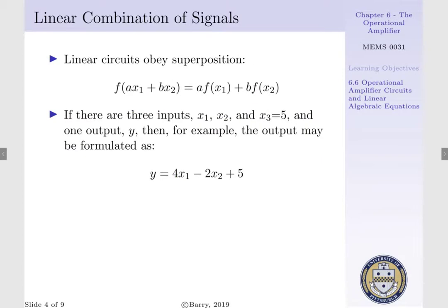Now, before we talk about designing operational amplifiers, we want to introduce the concept of superposition, that is, superposition of linear combinations of signals. Say we have a function f that can take ax1 plus bx2, where a and b are both constants and x1 and x2 are both inputs. If they are linear, i.e. don't depend upon one another, our function can then be expressed as a, our constant, times a function of x1, plus b, a constant, times our function of x2.